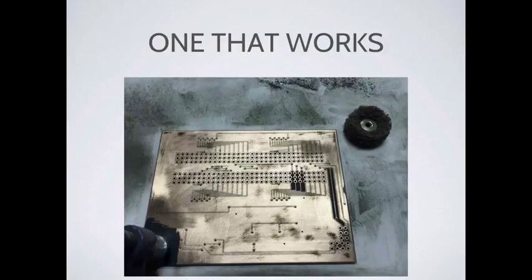But what I found really nice is that you don't want to be using this to eat away at the very, very top layer. You wanna wait till after you get off the very top layer of the solder mask, and then see some copper, and then start to use this buff to get rid of the next stage. And it's gonna leave behind all the copper, none of the copper is getting eaten away.